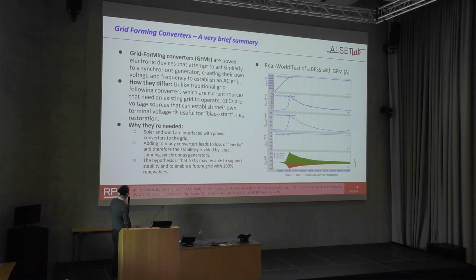And I think if you adopt the concept, because this is not a reality yet, the concept is that you put this type of converter technology both in PVs and in wind turbines, you might be able to additionally add other functions to it that will emulate a little bit of inertia. Because right now, with the kind of converters that you have, you basically don't have any inertia. You don't have any of the mimicking of the mass of a generator that can absorb and expel energy to maintain an equilibrium. So that's kind of the concept, right?